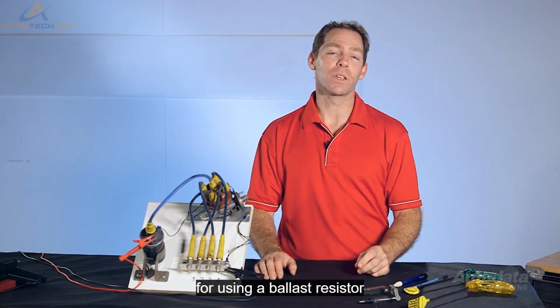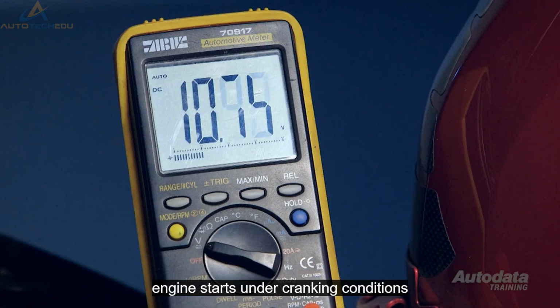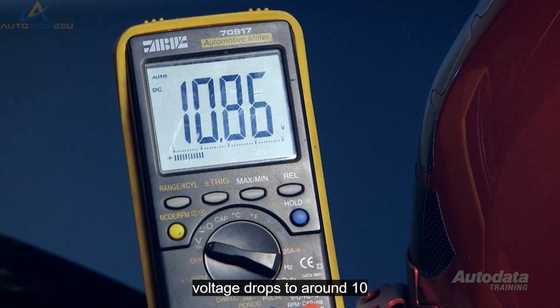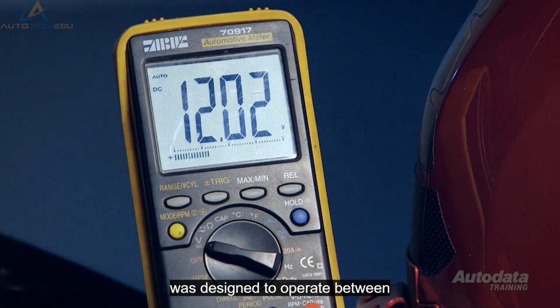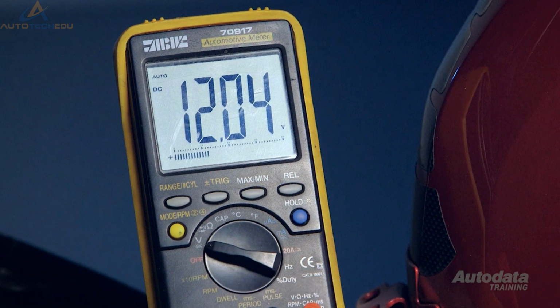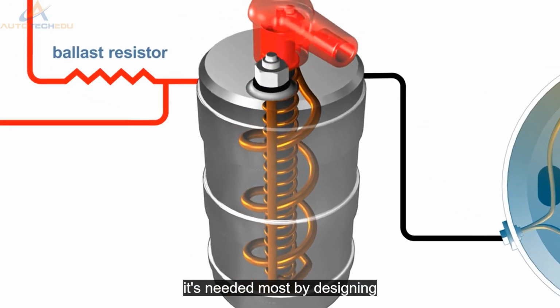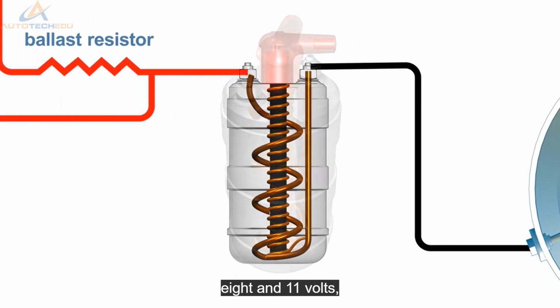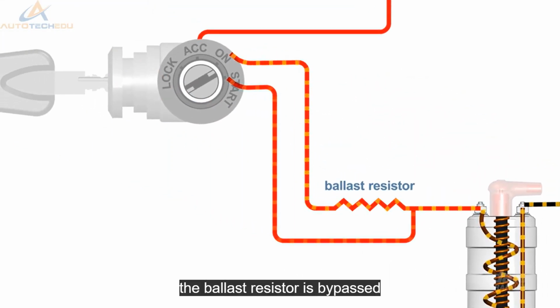A second reason for using a ballast resistor is to aid in cold engine starts. Under cranking conditions, the available ignition voltage drops to around 10 volts. If an ignition coil was designed to operate between 12 and 14 volts, this cranking voltage supply would limit the output of the ignition coil when it's needed most. By designing the coil to operate between 8 and 11 volts, the coil is able to produce its full output even under cranking conditions. In this design, the ballast resistor is bypassed during crank conditions.